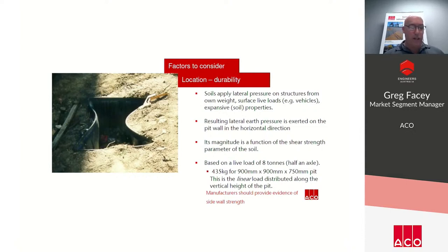Any concrete haunches around should be a minimum concrete strength of 25 MPa as a recommendation, because soils do apply lateral pressure on structures just from their own weight, live loads and expansive soil properties.